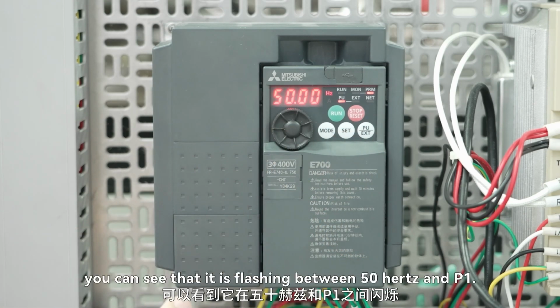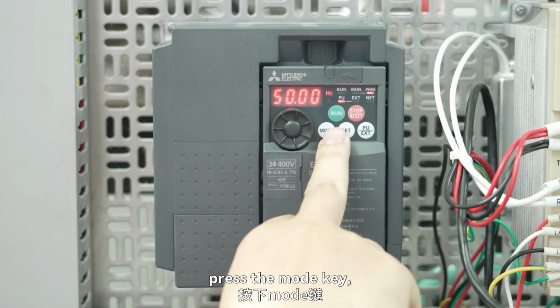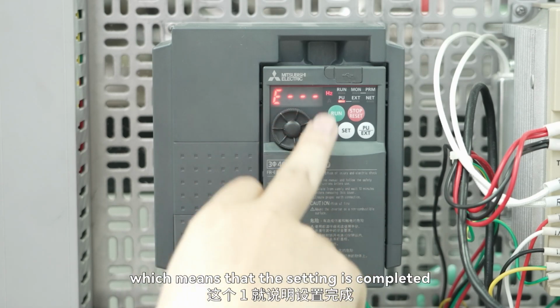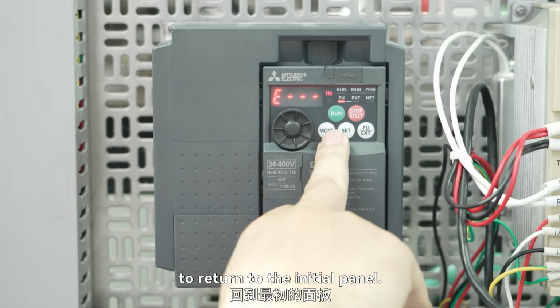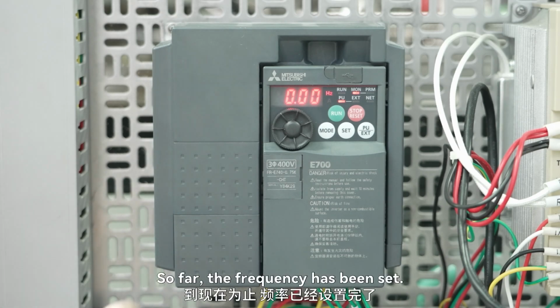Okay, after pressing it, you can see that it is flashing between 50 Hz and P1. During the flashing process, press the mode key, and it will display a 1, which means that the setting is completed and it exits the setting state. Press the mode key again to return to the initial panel. So far, the frequency has been set.